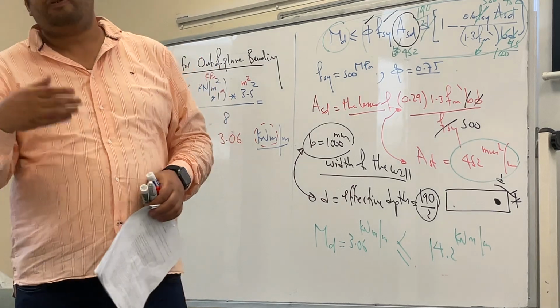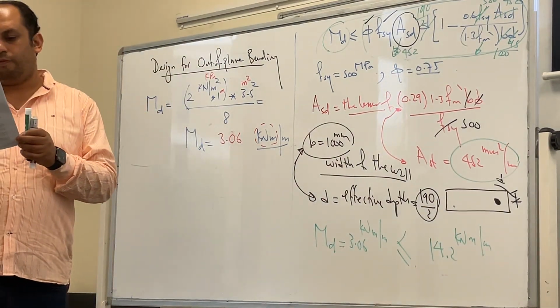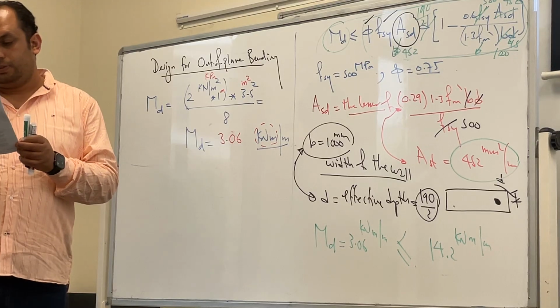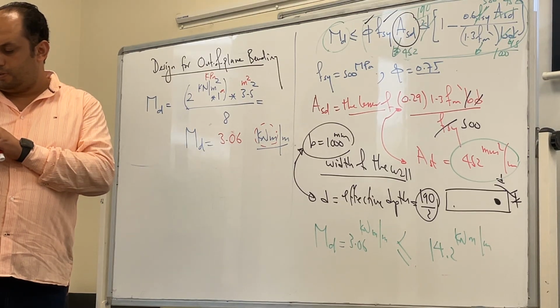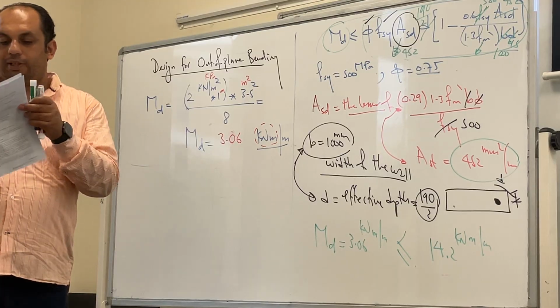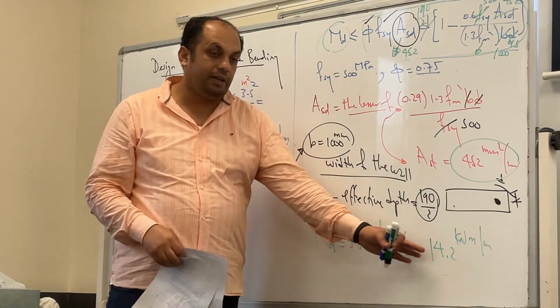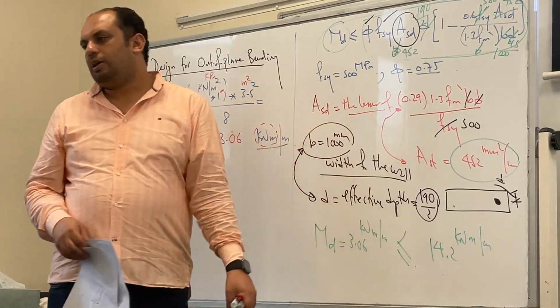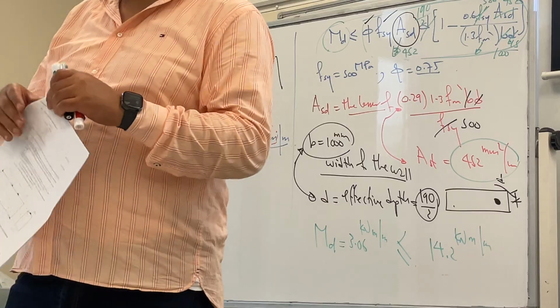Another option, because we also have a maximum reinforcement, is there any maximum reinforcement here? If it is excessive, for example if this is 20 and this is 10, we can increase the wall thickness. Instead of 190, we use the next block thickness.